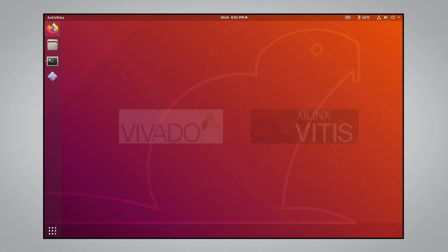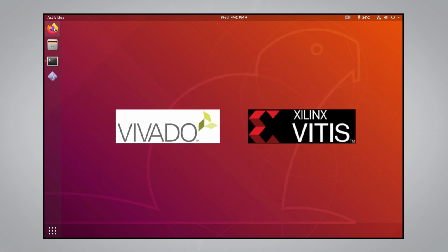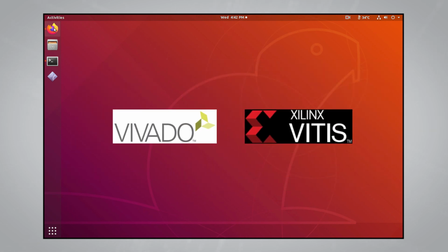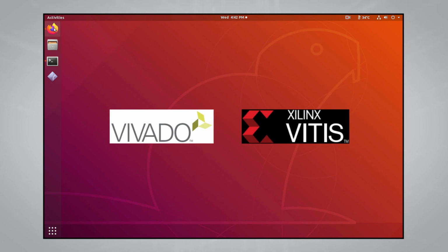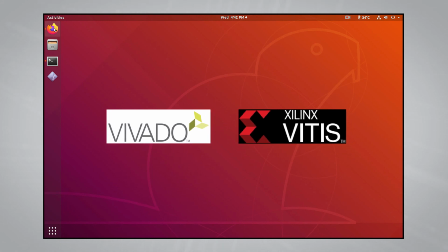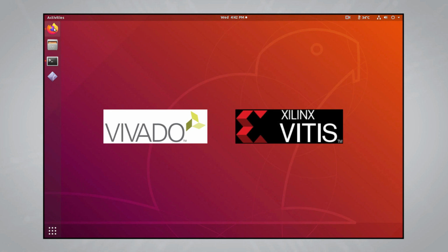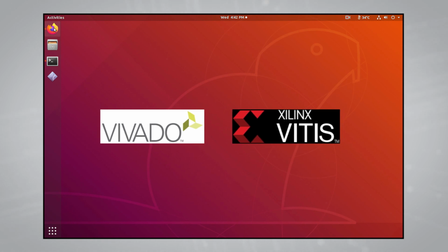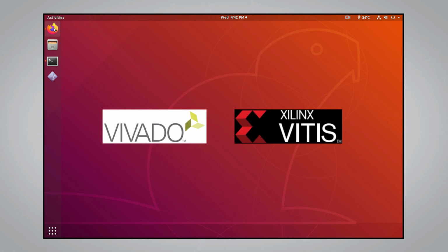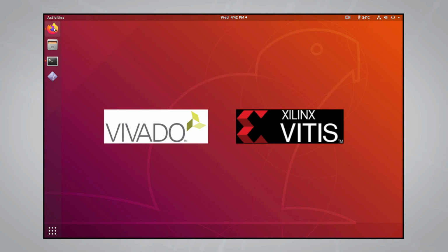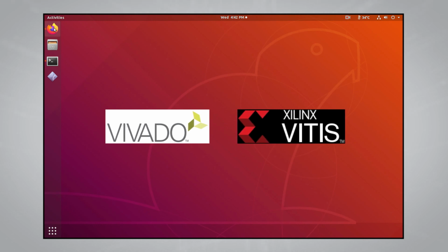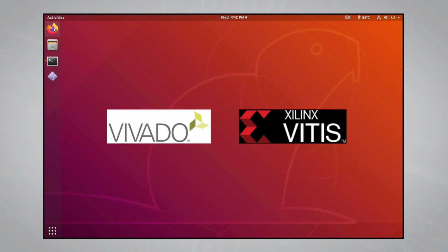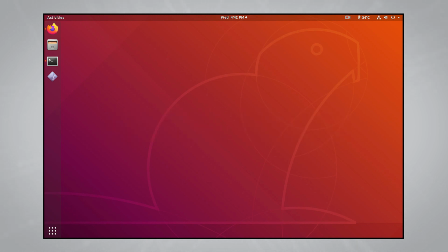For creating the FPGA bitstream for the PL and Xilinx's first stage bootloader, we need to download and install some software tools called Vivado and Vitis. Vivado helps you create the bitstream, and Vitis helps you create the first stage bootloader, or any other applications you'd like to run on the CPU on the PS side, whether that be bare metal or higher level application. Luckily, both of those software tools are free and can be installed by one software package on Xilinx's website. So let's do that now.